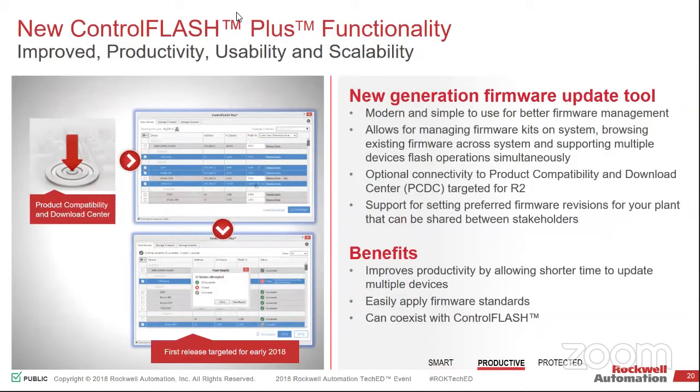So a question from the webinar: is OPC UA compatible with Advance? To an Advance processor, no, that is still either Modbus TCP/IP or Ethernet IP. But Advance is able to tie into Factory Talk itself. So from an outbound connection, yes, the same way that we would deal with the rest of the controllers, ControlLogix and CompactLogix. Thank you.